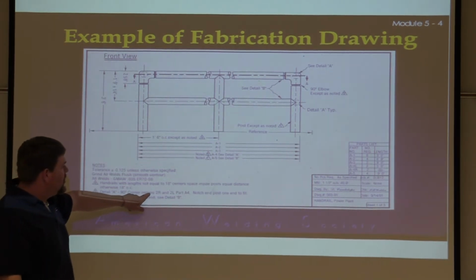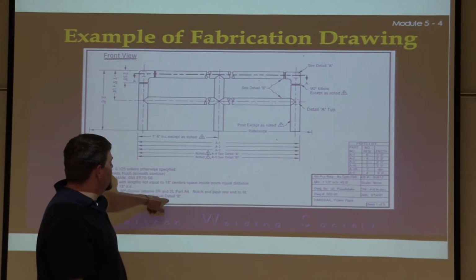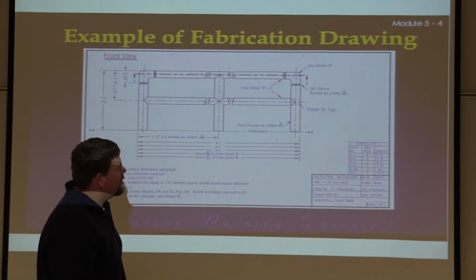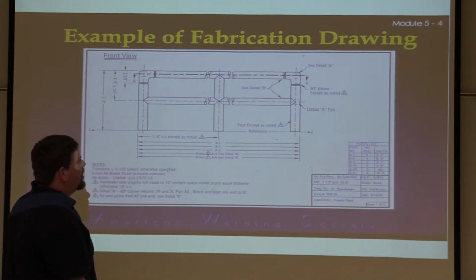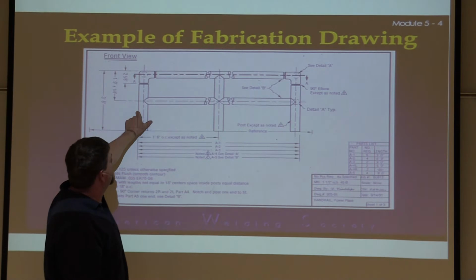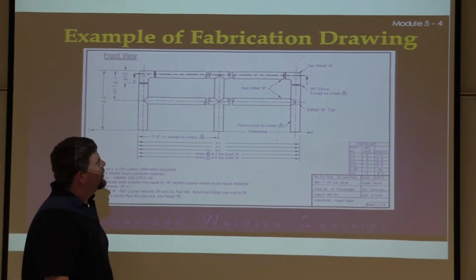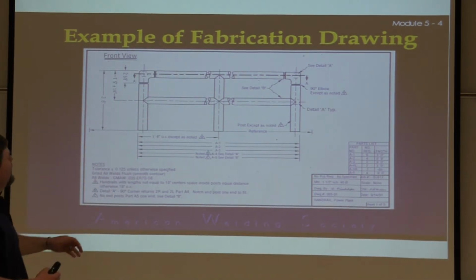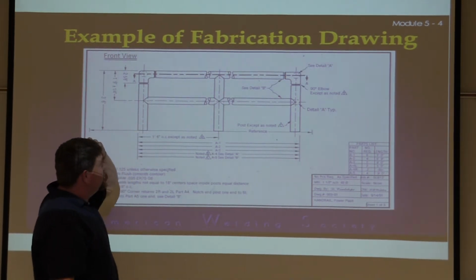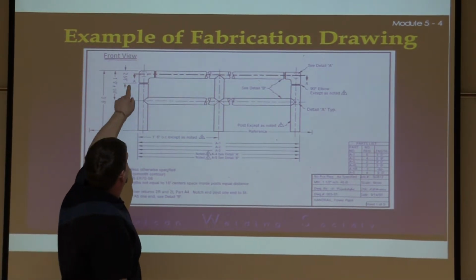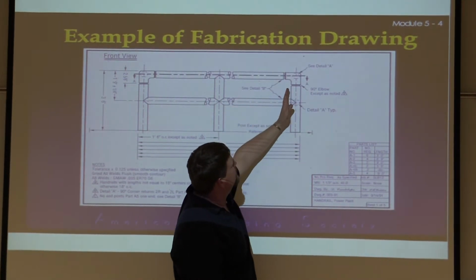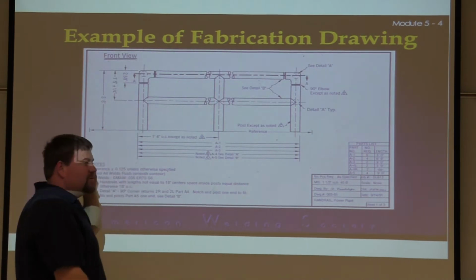Detail is a 90-degree corner. Returns 2 radius and 2 L part A4. Okay, so then you have to come back over to your part, which is A4 required, and they tell you a different length. They have the length offsets differently here than they do here. Okay, and again, you don't even see a symbol here that shows you this is a right triangle. You assume a right triangle because this is a 90-degree elbow. So you assume that this and this are perpendicular to themselves at this point.